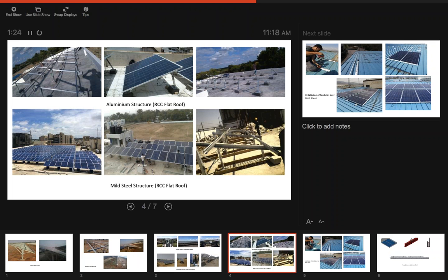Satish, I will request you to be a little more simplistic. We have a lot of audience who might not be as technical as you are. Very simply, can you give us a thumb rule: at a wind speed of, let's say, 150 kilometers per hour, what would be the approximate foundation size? For wind speeds alone, we can't derive the foundation size. Based on the supporting span, we can derive the support uplift capacity for those foundations.